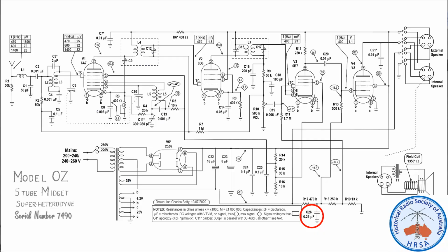There was a filter cap in the back bias circuit, which is this fella here, and that was leaky. Now, normally a slightly leaky paper cap wouldn't matter that much, but in this circuit, where you've got 470k to 50k high resistances, its leakage was pulling the back bias down quite a lot.